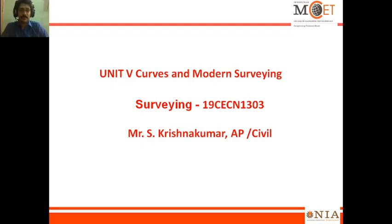Hello friends, we are continuing the topic in the curves. Till now we have completed the linear methods in the curve and we have started the angular methodology. In that we have started with the Rankine's deflection angle method, and it totally depends upon the instrument. Now, the advancement of Rankine's method, that is the two theodolite method.